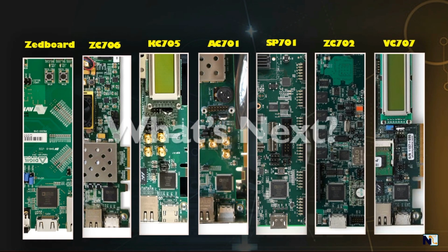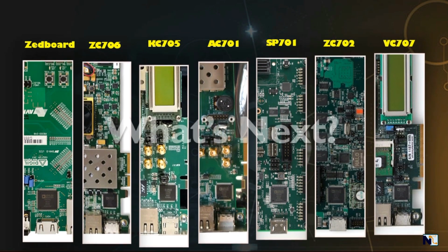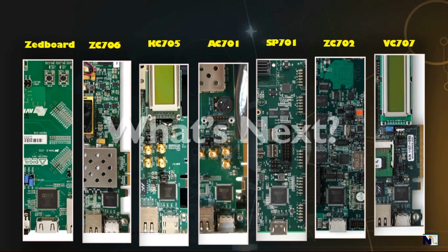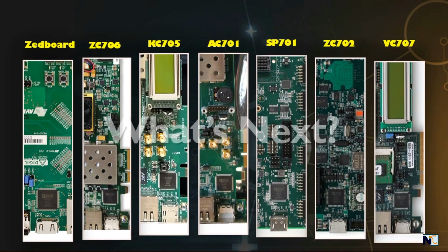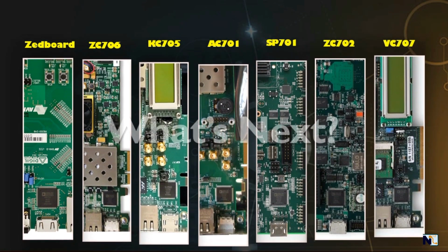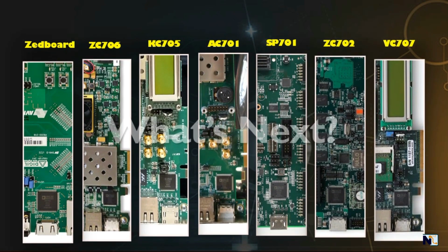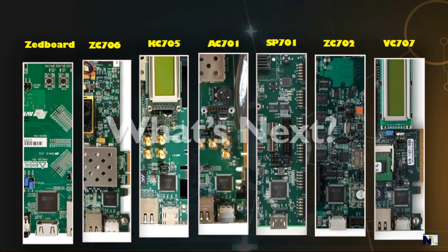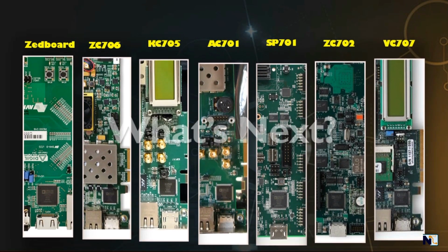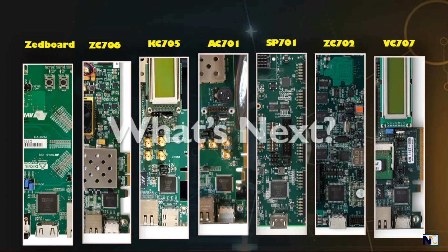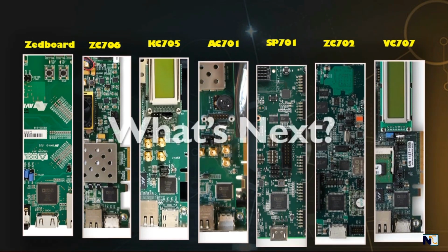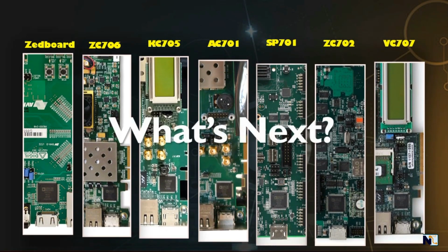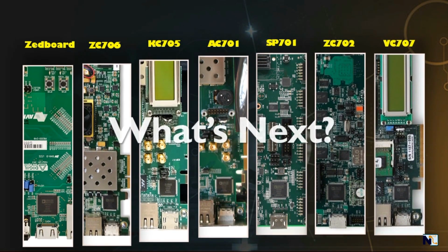This design presented the fundamental FPGA design to work with the HDMI 1.4 standard by interfacing the ADV7511 HDMI TX IC. You can follow this design flow to work with other Xilinx or other vendors' FPGA boards that include the ADV7511 HDMI transmitter IC. It can be integrated with higher FPGA designs. In your custom design, you can replace the TPG or the test pattern IP with the actual input source. This design uses a standalone design approach for better startup. In a future design, I will bring up the design with the Linux approach, and we will also discuss HDMI 2.0 and HDMI 2.1.